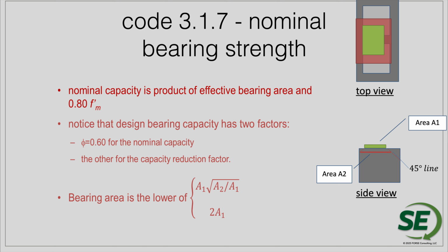So again, looking at the bearing plate capacity is another thing that we can have a standard connection that we can define for a masonry wall. Looking at the different types of capacities that you can reference, having a bearing plate on a wall really comes down to a bearing area, whether it's going to be a confined bearing area or something that's unconfined. So if the bearing plate is going to be near the face of the masonry wall, it's going to be what I would call an unconfined condition, versus if the bearing plate is slid interior to the wall, then you'd have a confined bearing capacity, which is more capacity for your design.